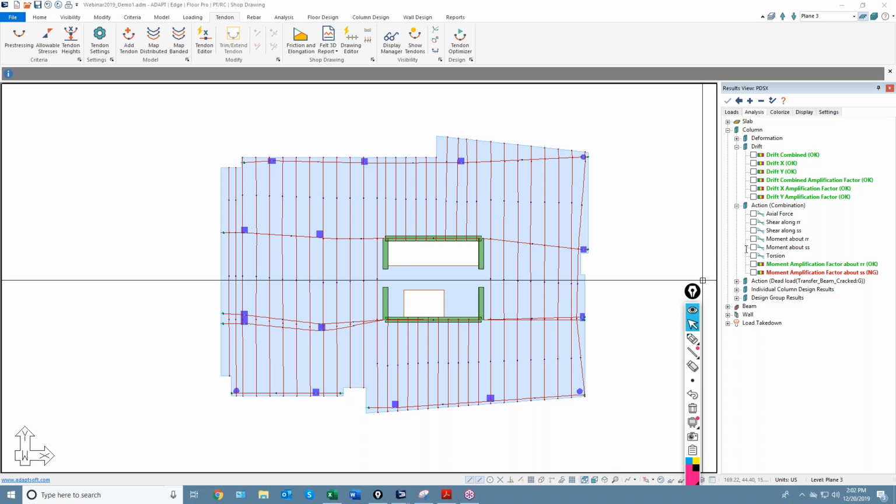One of the limitations and drawbacks is that the ramp provides you just with raw analytical results. When it gets into design of those other components, especially at the ramp level, you would have to use other means to design the ramp. But analytically, it would be considered part of a continuous multi-level diaphragm, if you will.